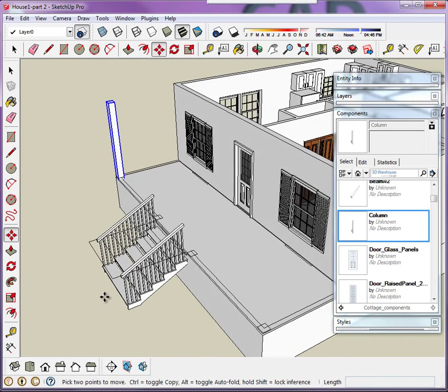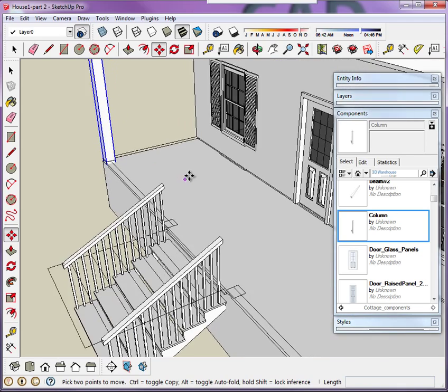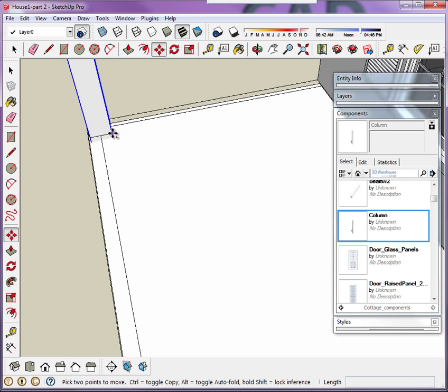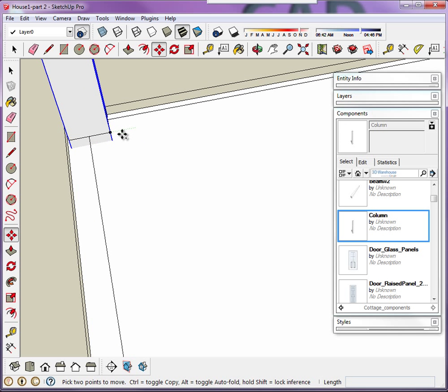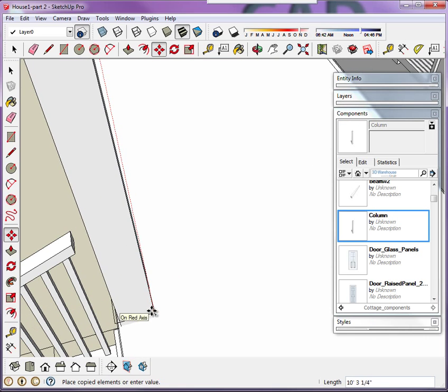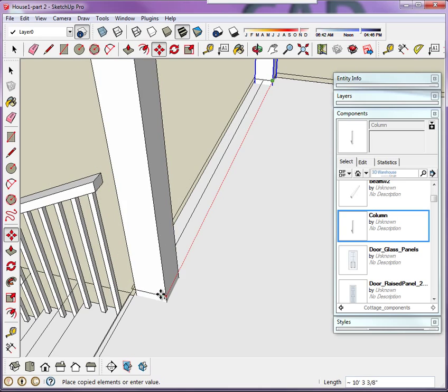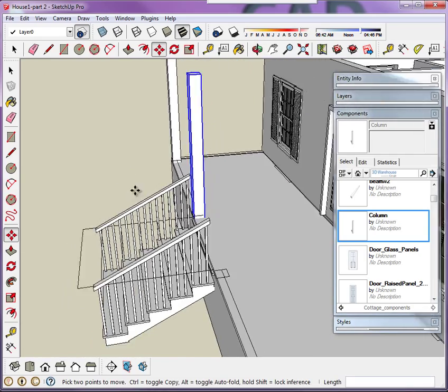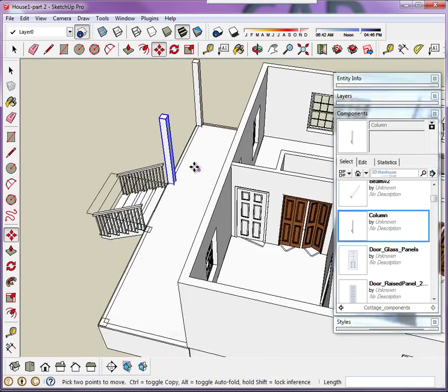And then it's just a matter of creating copies. So again, the way I create a copy here is I use move command plus control. Just tap it once. Notice that I'm using the XREF as a base point, right? I'm using this point here. Click from there, drag it along to the next point. And then I can repeat it once again.